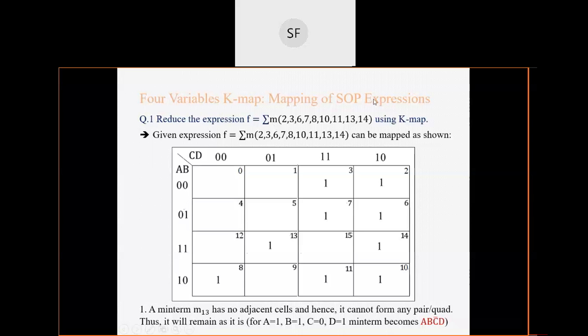So this much min terms are present, and from the value of min term, you can understand that this will be a 4 variable function, right? Because for a 4 variable function, total min terms will be from 0 to 15. You can observe that this is in sum of product form, because min term is there, small m is there, and again it is 4 variable.